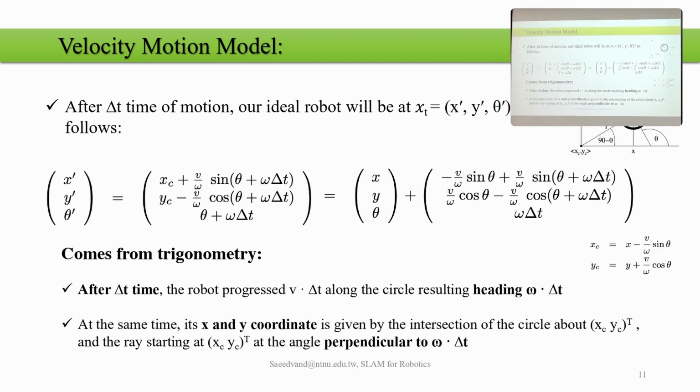So now, one important element remaining is that this equation, if you write it simply, just plugging in the values based on the previous pose, will work. But what's the problem? The problem is that we say the control commands are not accurate. The robot cannot run them accurately most of the time. We have error over there. But here, everything is exact.